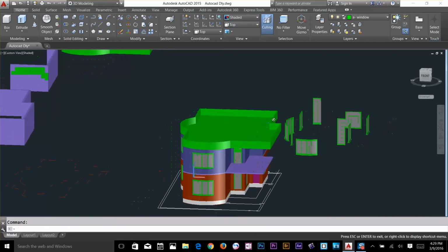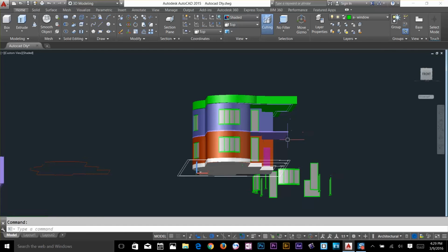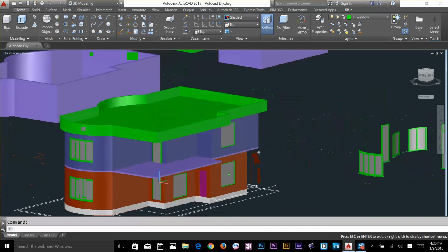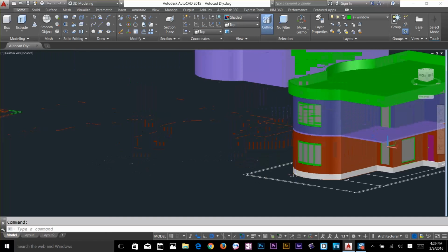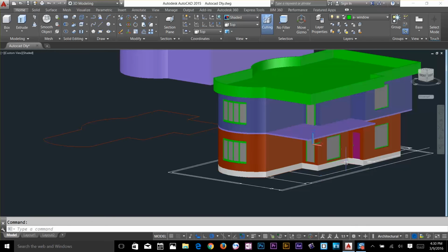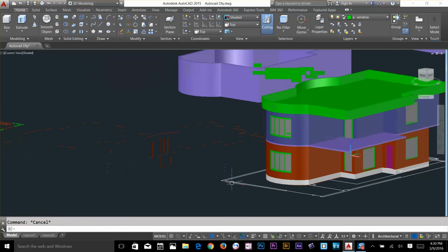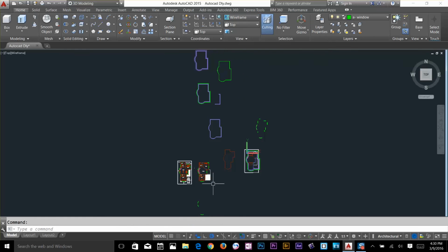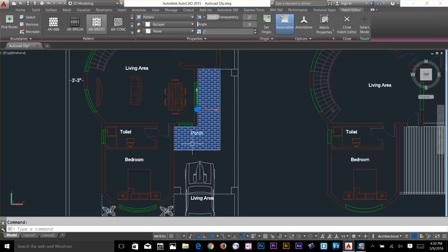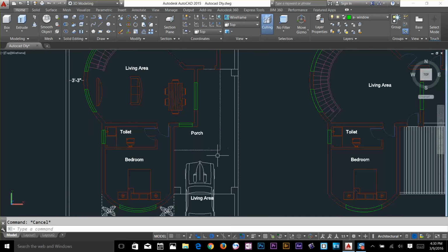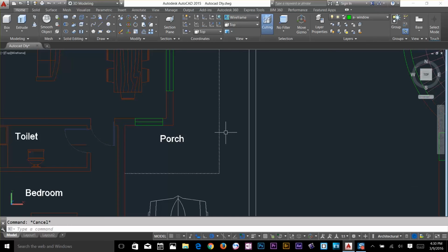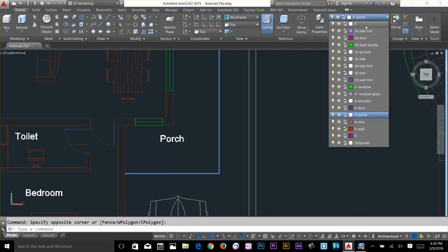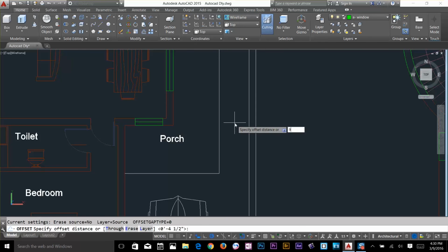Yep, so now what I want to do is start making my pillars. So for my pillars, this is 10 feet high plus this 2 feet of this. First, let's make some steps here. So for the steps, I'll go back to my top view, change that to 3D wireframe, and delete this porch. And now these are basically the steps we need. So I will change this to my 0 layer, and then I will offset about 9 inch.